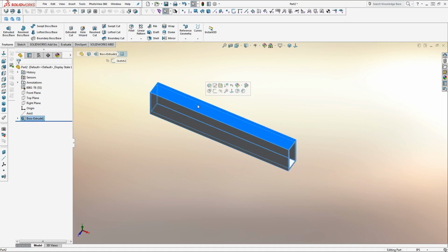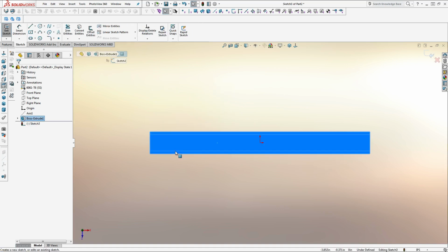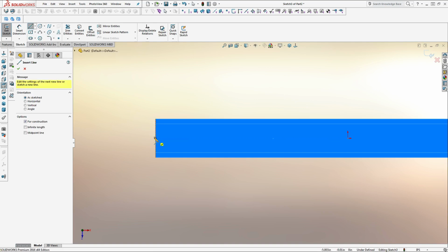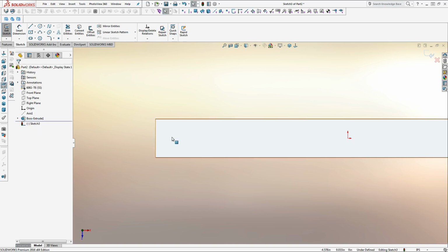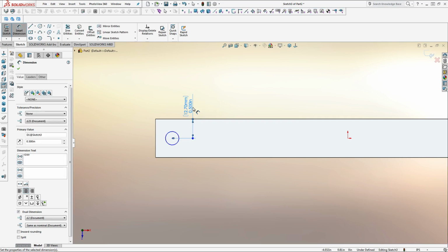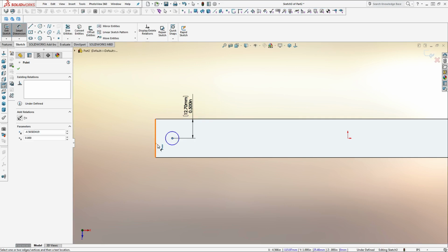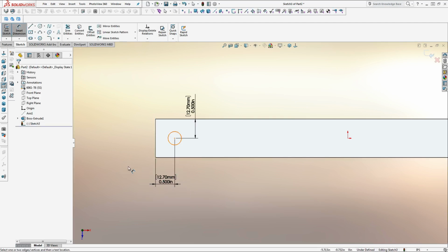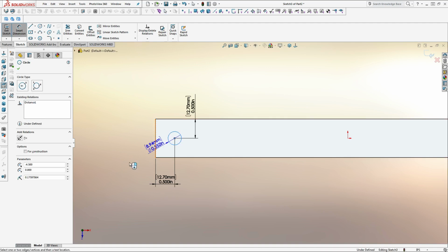So in order to do that, a couple ways you can do it. I'm going to show you two, and I'll tell you why you should just stick with one 9 out of 10 times. So one thing you can do is you want your hole to be in the center, and of course you can dimension it. The center is a 1/2 inch from there, and you want to start a 1/2 inch from the other side, just for symmetry. Because if you start a 1/2 inch from one side and you do a 1/2 inch hole pattern, then you can have it line up really nicely on the other side. It's all divisible by half.